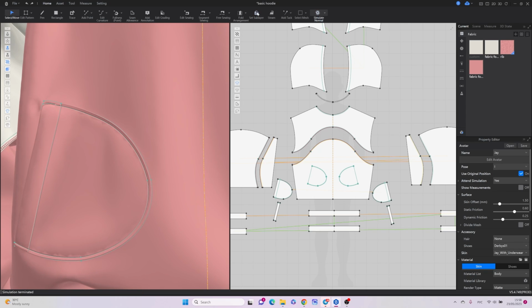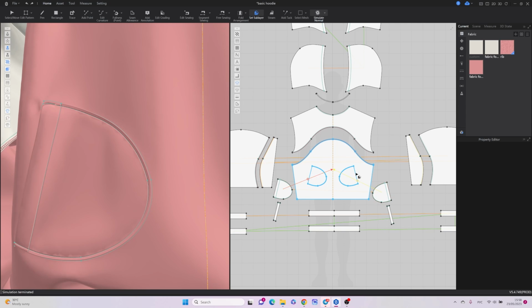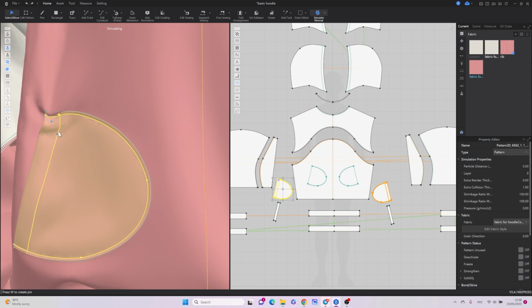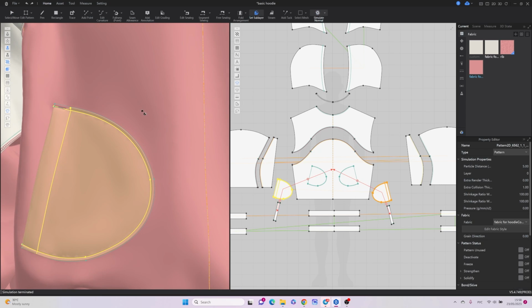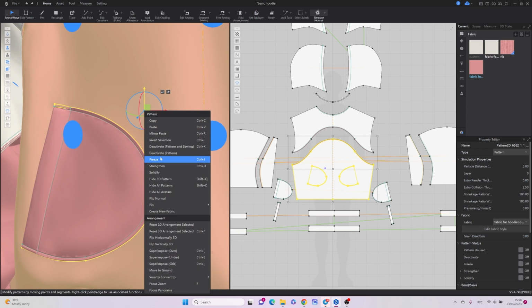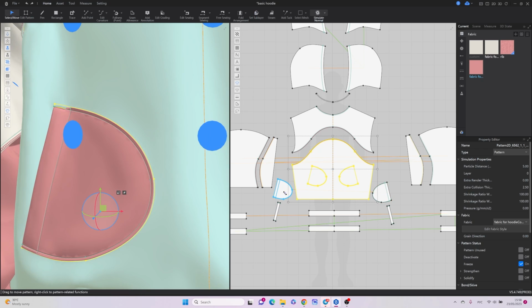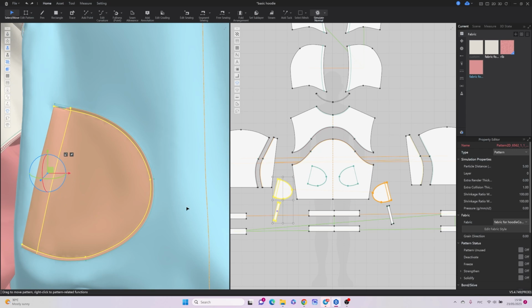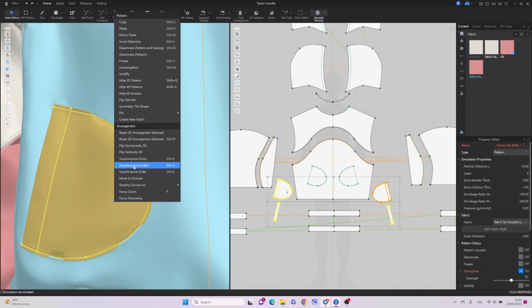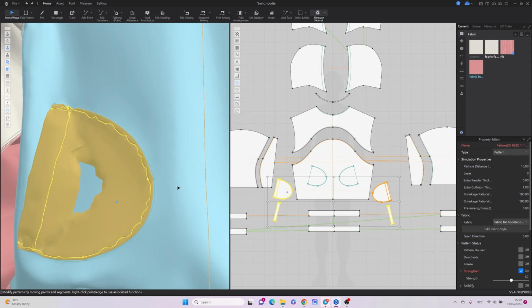If there are problems in simulation, because there are 3 layers of fabric, sometimes you need to set sub-layer and choose which layer of the fabric comes on top. Also, it helps to freeze one layer of fabric before simulation. Then you can superimpose it over, simulate it, and now it's good.